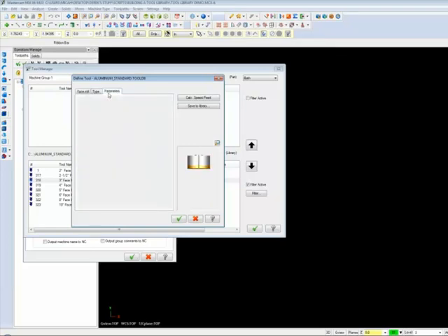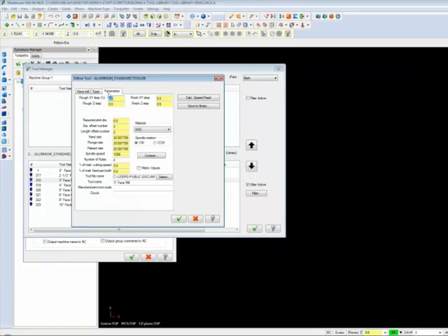On the parameters page, we'll set up similar parameters with the 2-inch face mill. Rough XY step over at 75% of tool diameter, finish XY step of 2 1/4 inches, rough Z step of 150 thousandths, and a finish Z step of 10 thousandths. These values will automatically pop up when we generate toolpaths. The inserts are made from carbide, and there are 8 of them.